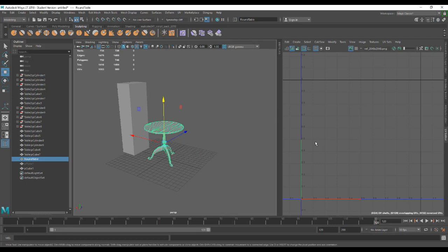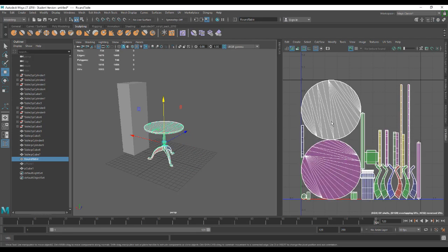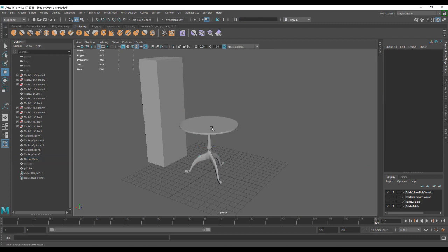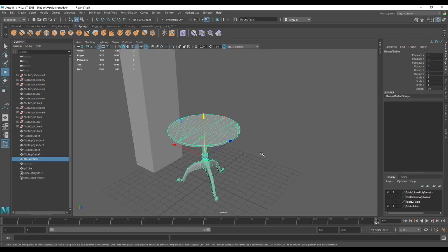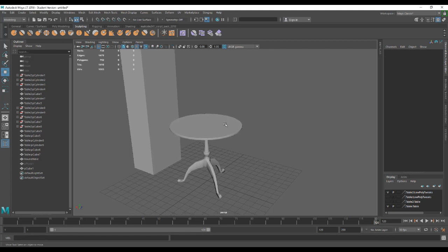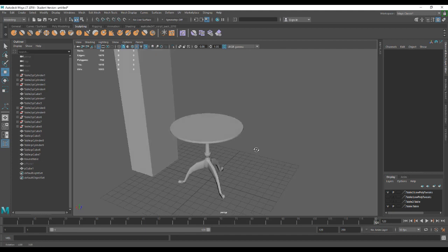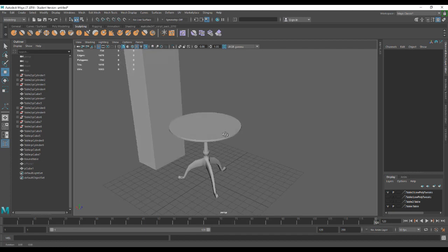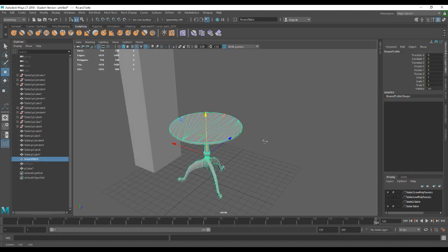I have already got UVs on this, so our UVs are laid out, ready to go. Obviously if you're applying materials within Unreal, then you need to have those UVs there. You can't create UVs within Unreal itself. It will do that for light mapping, but that's a completely different thing. So do create your UVs ready to go.